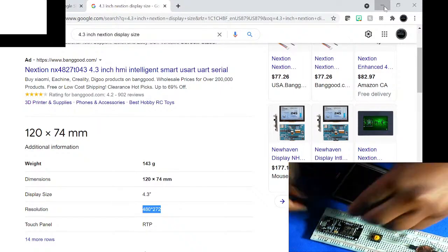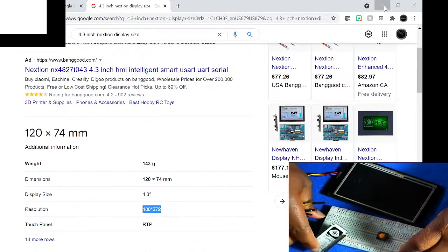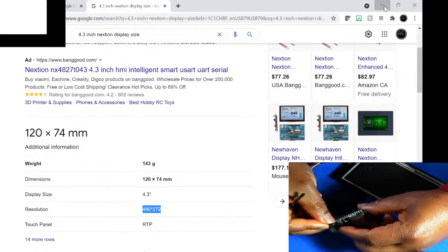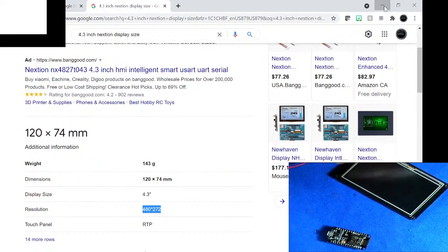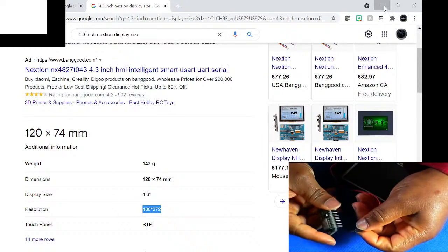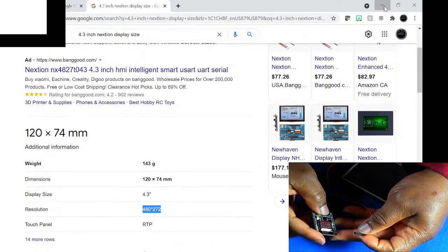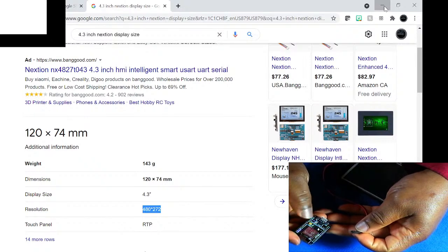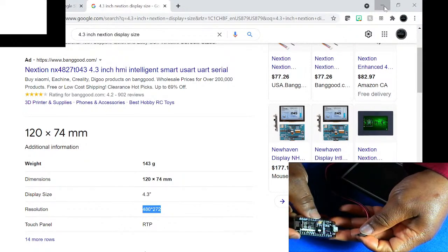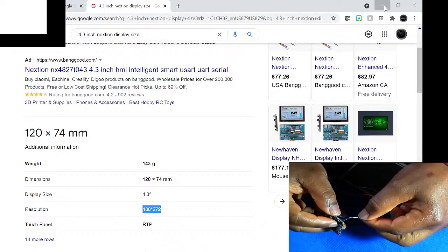So to reduce the amount of wires I'm going to use, I don't have to have it here on the board. I can just unplug the Arduino and then just take the power, 5 volts and ground, and plug them in directly. So on the Arduino, I have 5 volts V in and ground. So ground, V in is 5 volts.